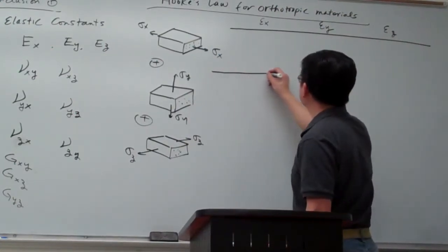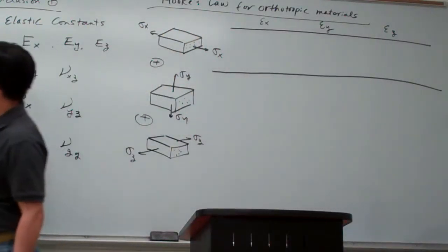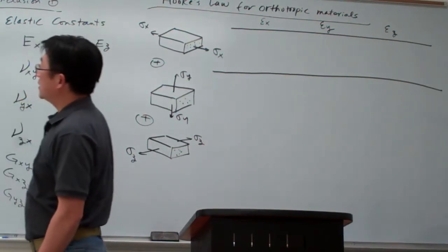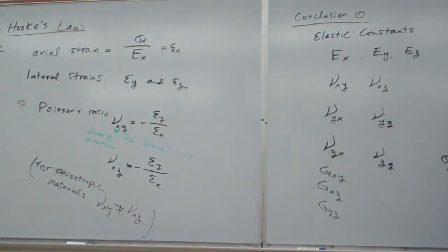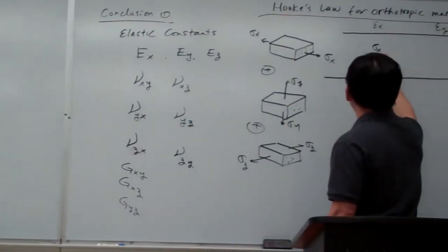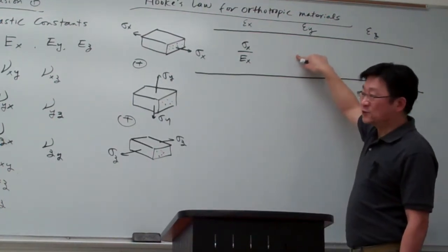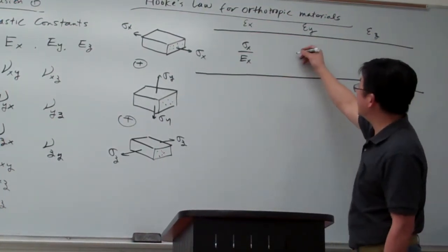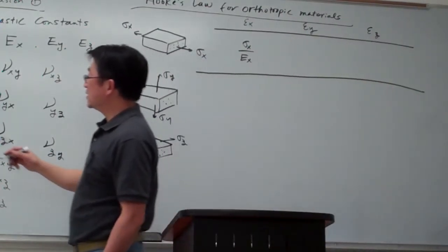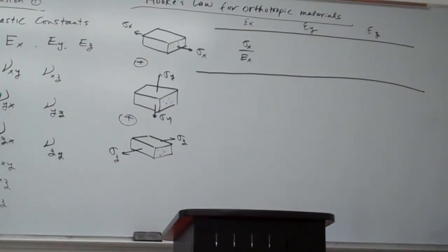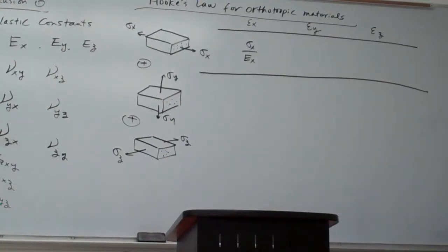Now for the first case, here we can follow this condition. Basically this is the strain in the x direction. Okay, so that will be the stress divided by Ex. And this one, what is this? So this one we can utilize that equation here. Basically here we can say epsilon y equals minus mu xy times epsilon x.